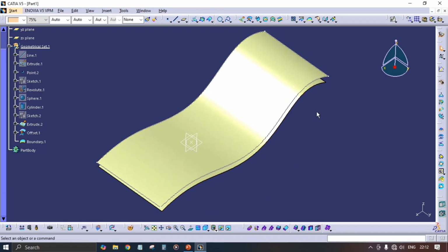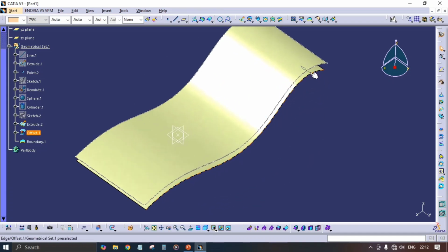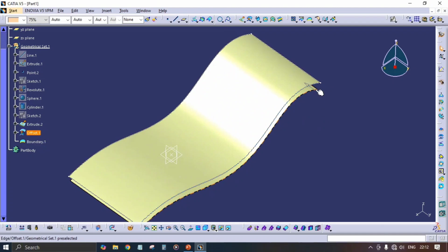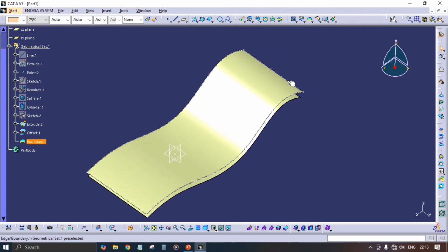Now I want to create one surface which is not tangent to this surface, but goes 90 degrees from it onwards. Sweep means that when you have one wireframe profile, you can create an extrusion of surface in any other direction.